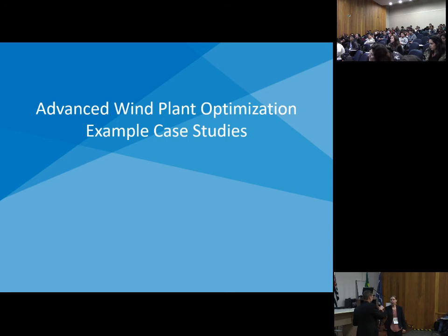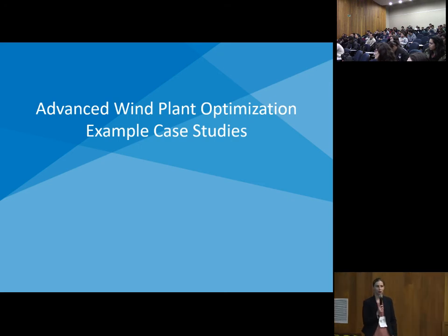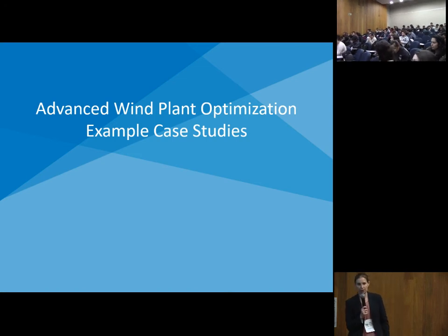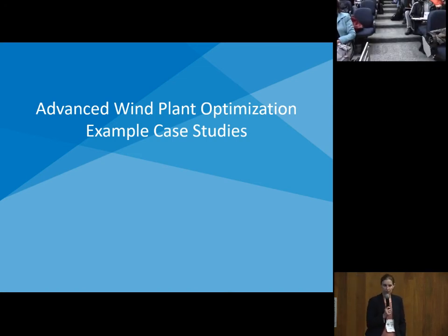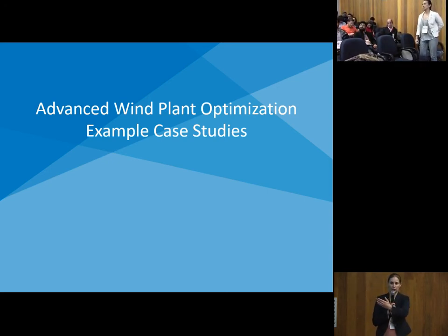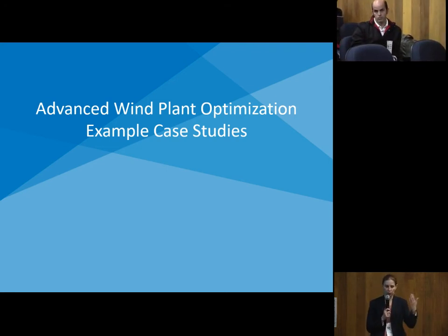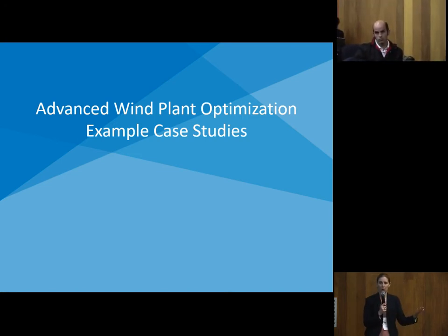Maintenance. Okay. Yeah, there's certainly a lot of research both at NREL and in the larger community on what we generally call reliability and operations and maintenance. There's a whole lot of research investigating different failure modes for different components of the turbines. We have a gearbox reliability collaborative, a drivetrain reliability collaborative with industry, and a blade reliability collaborative. Because of the complex loading of turbines, the complexity and the uncertainty in the physics, you have a lot of premature failures with the technology, and understanding the root cause mechanisms of those failures is open-ended in many cases.